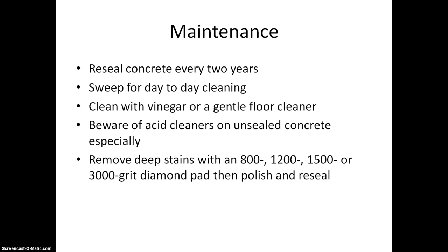Clean with vinegar or a gentle floor cleaner. You want to watch out for acid cleaners, especially on unsealed concrete, because it will discolor the concrete. And then I found in a book for concrete countertops, but I'm sure this could work on floors too. To remove deep stains, you use one of these diamond grit pads. Scrub the stain off, and then you wash it with water, and then you can polish and reseal the concrete.